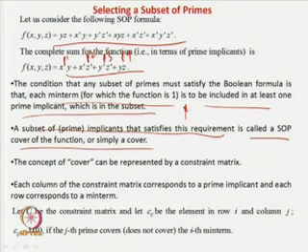That is, if you take say P1, P2, and it covers all the min terms of this function, then you say that P1, P2 forms a cover. If you find that P1, P2, P4 is actually required for that, then you will say that P1, P2, P4 is a cover. There can be many other options also, like P4, P3, P2 can also be a cover. Now among all the choices, which one will we keep?